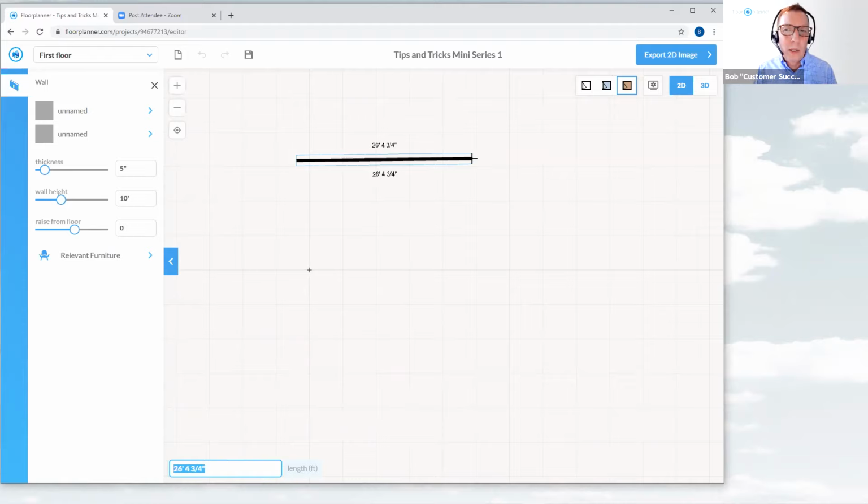And you always want to make your walls very clean. One point to one point end. Start one point to one point end. Again, try not to fill in a lot of little pieces to try to fill in your wall. That'll add a lot of confusion when the automated floors and ceilings are being created, trying to match up. So try to keep it as clean as possible.